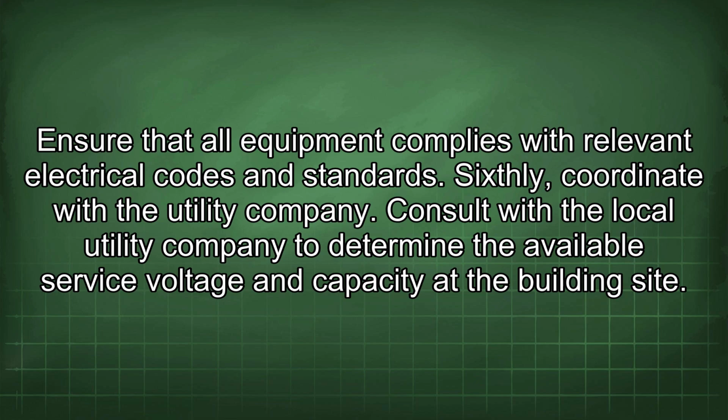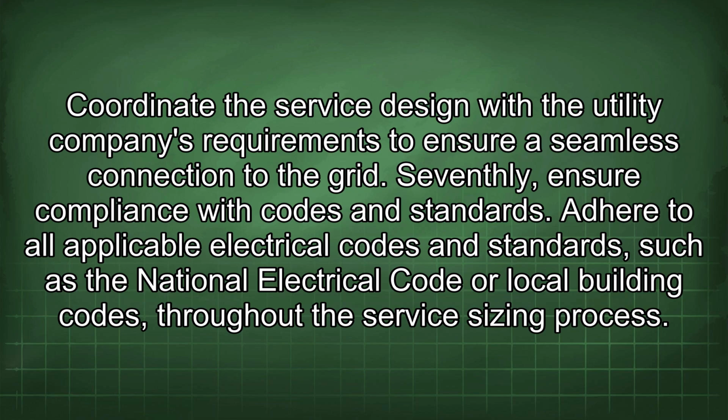Sixthly, coordinate with the utility company. Consult with the local utility company to determine the available service voltage and capacity at the building site. Coordinate the service design with the utility company's requirements to ensure a seamless connection to the grid.